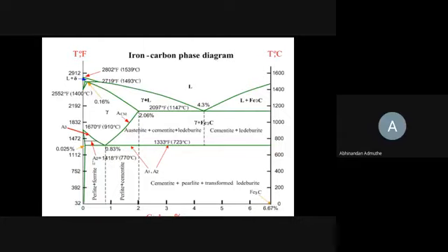Okay, so this is alpha, you can see it here. This arrow mark: alpha ferrite, gamma iron, which we call FCC here, and delta ferrite somewhere here, which is a BCC structure again. From room temperature to 910, we have only one phase, alpha ferrite. But you can see all these are Greek letters: alpha, gamma and delta.